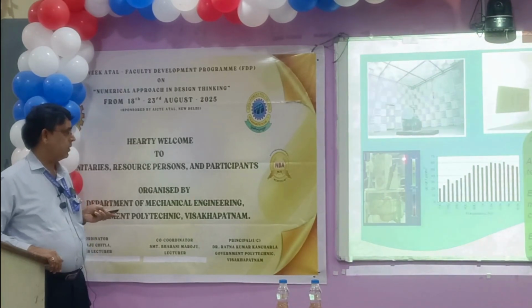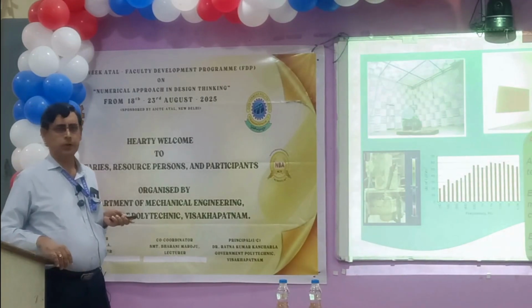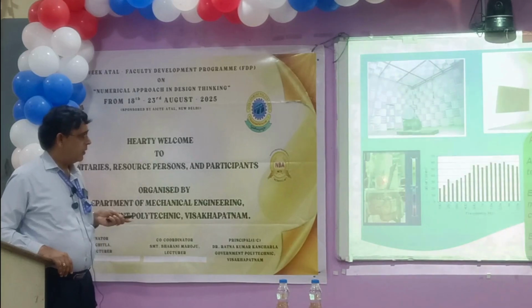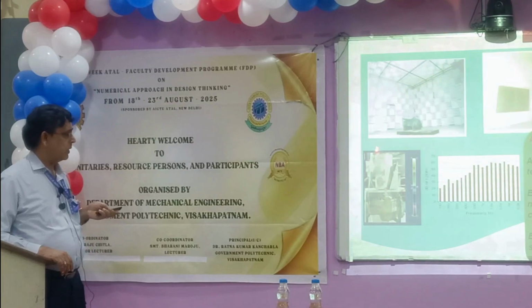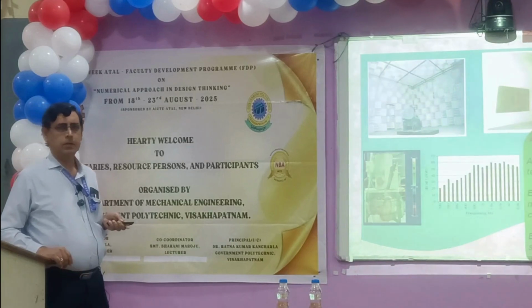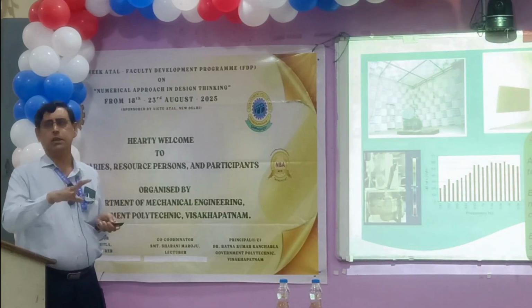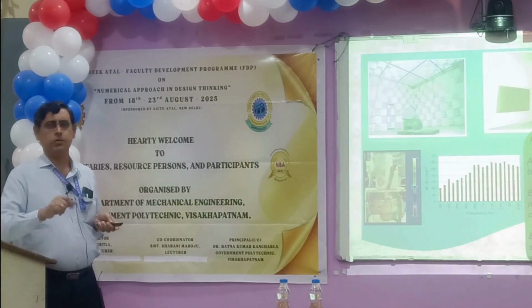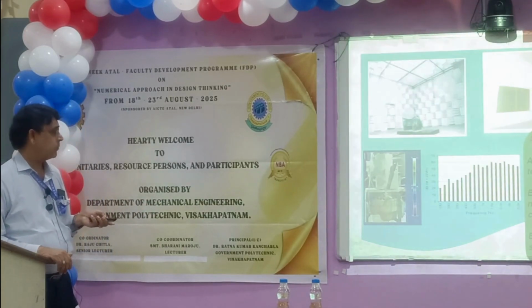In fact, if you measure the sound like this, it will create a map of sound from where you can identify where is the actual source of noise. In this case, for example, in this vertical pump, the major noise is coming from here. So then you can map onto that particular component and attack that component design to reduce the noise. This is the advantage of having such facilities.